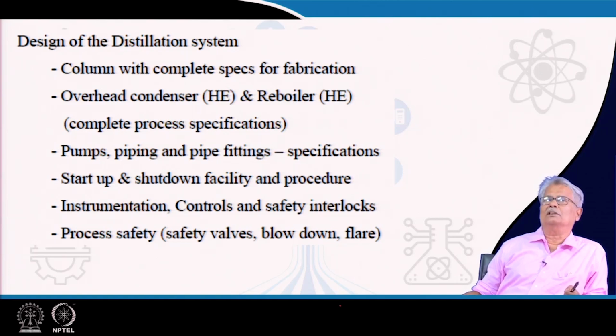You have to provide in the form of a P&ID the instrumentation control and the safety interlocks which are implemented through instrumentation, and definitely the safety valves or blow down arrangement and the flare for process safety, whatever is required for your plant, the distillation system has to be provided.